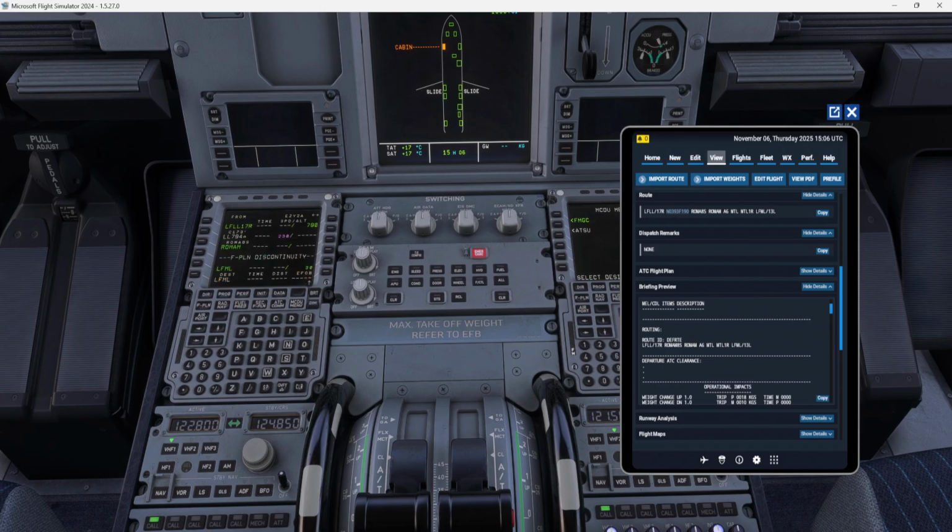Insert. Then from Romam we have an airway Alpha 6 to MTL, Mike Tango Lima. Inserts, and we arrive to Marseille 13 left. Let's take 13 left, Zulu approach, star MTL 1 Romeo. Inserts. Second flight plan, copy active.